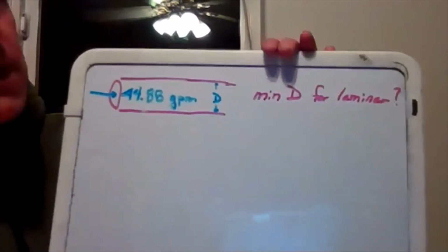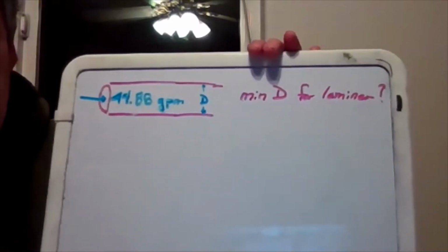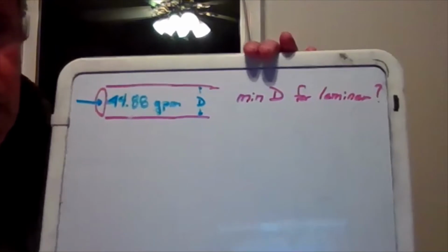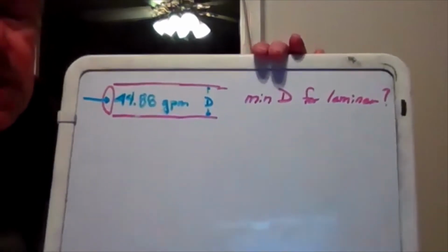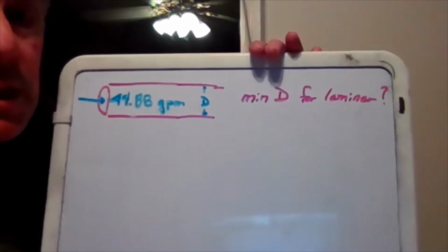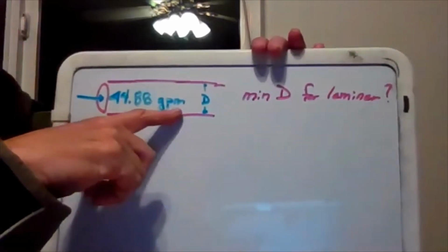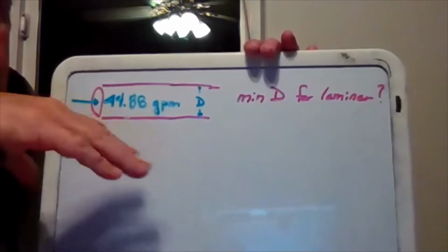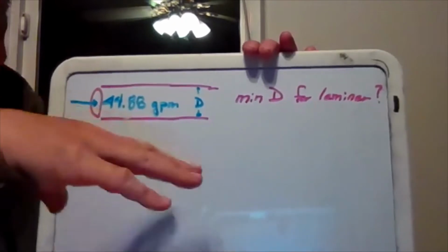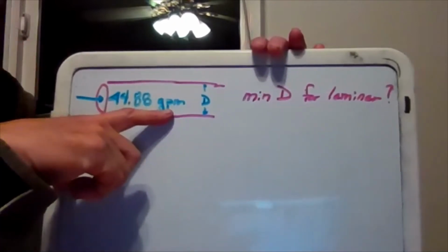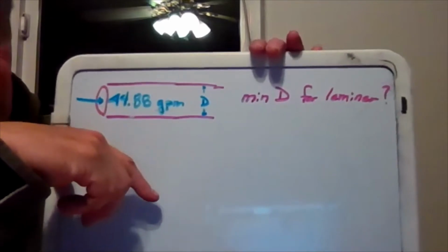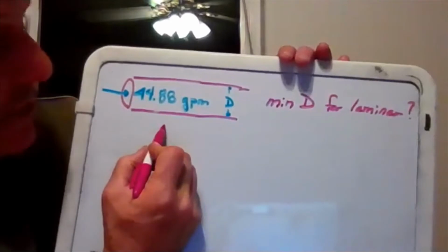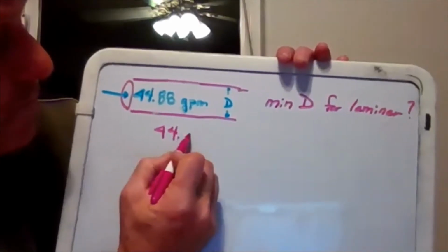So if you want a challenge, just go ahead and pause the video and see if you can get all the way through this yourself. But once again, I'm going to break it down a little bit. First thing that I'm going to do is change the units on this volumetric flow, gallons per minute. Remember, our length unit is in feet, so we would want this to be in cubic feet per second. So that conversion, we could write it all out in detail, but we'll just reason our way through it.